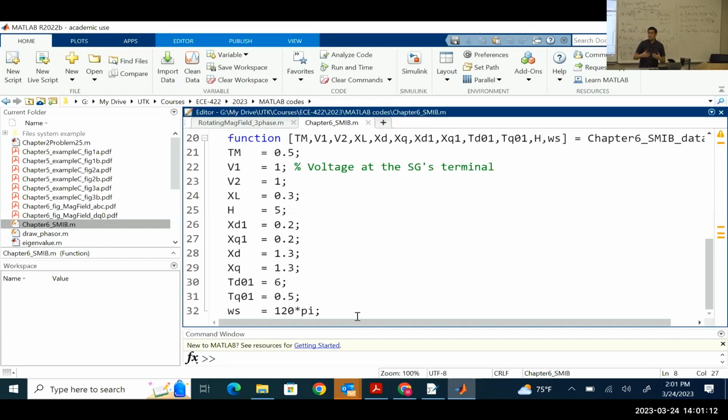But those dampers are going to target different times after a disturbance. The first part is called the subtransient response. There, we're going to have a huge torque that will try to damp the machine, but it's going to happen over a few cycles. But then by design, we will have other dampers with different physical characteristics that will respond in a longer time. So we will have a huge, important action at the beginning, in the first cycle, and then a more sustained action over several cycles after that.